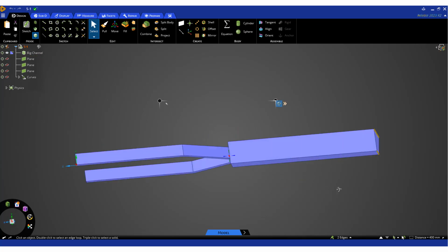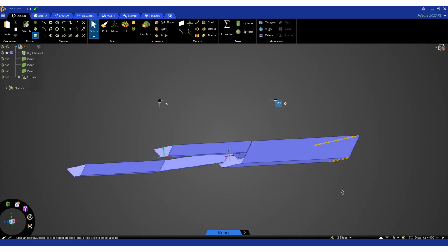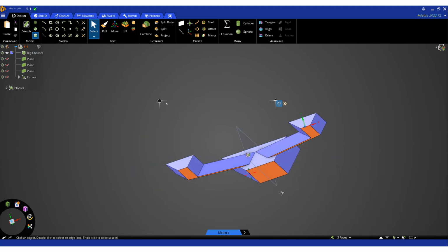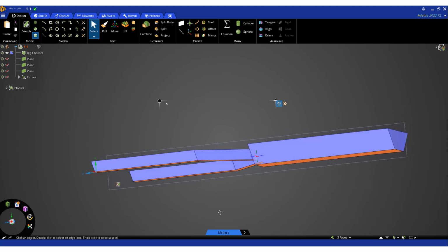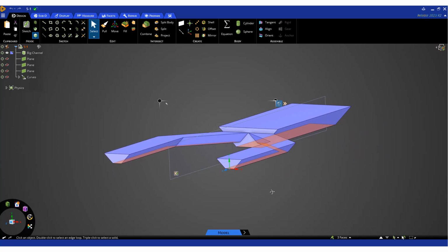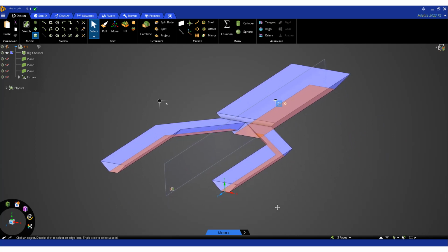millimeter. So this is the case that we already talked about, and the bottoms of the branching channels are not at the same level as the bigger channel. So larger cross-sectional area, and we're expecting much more water, which we already saw in the results of this case. Let's look at the second case.